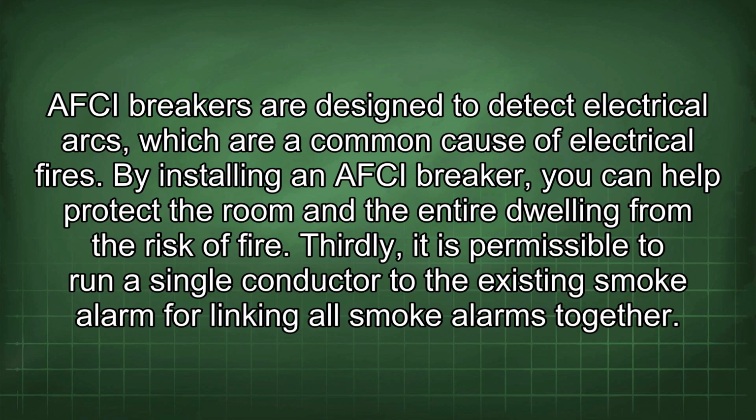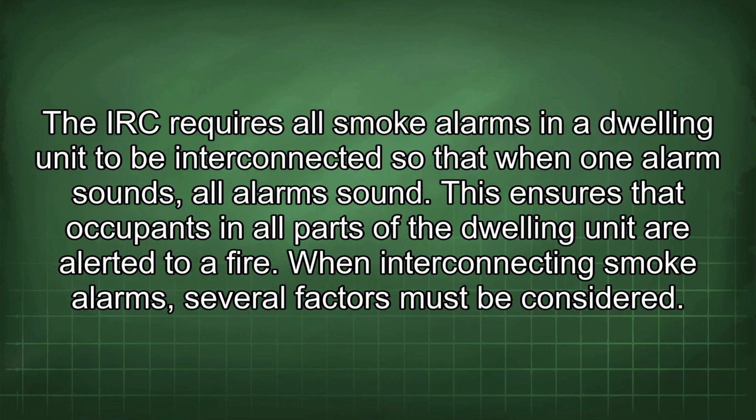Thirdly, it is permissible to run a single conductor to the existing smoke alarm for linking all smoke alarms together. The IRC requires all smoke alarms in a dwelling unit to be interconnected so that when one alarm sounds, all alarms sound. This ensures that occupants in all parts of the dwelling unit are alerted to a fire. When interconnecting smoke alarms, several factors must be considered.